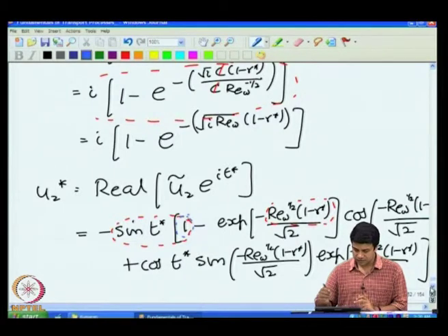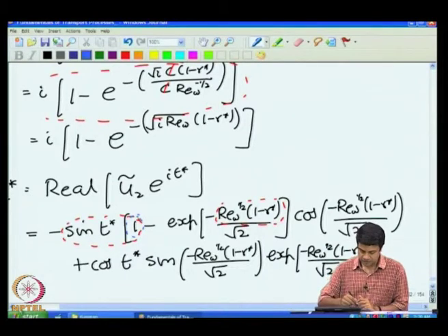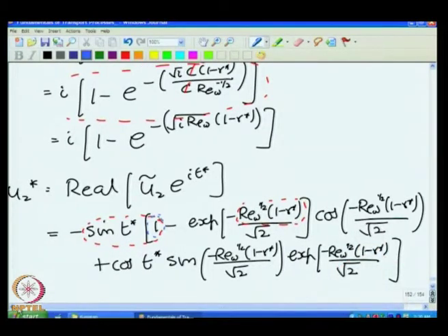The reason is because just as in a Cartesian coordinate system, in this case as well, if the thickness of that boundary layer is small compared to the radius of curvature of the tube, very close to the surface, it appears to be diffusion from a flat surface, because the radius of curvature of that surface is very large compared to the thickness of the boundary layer.